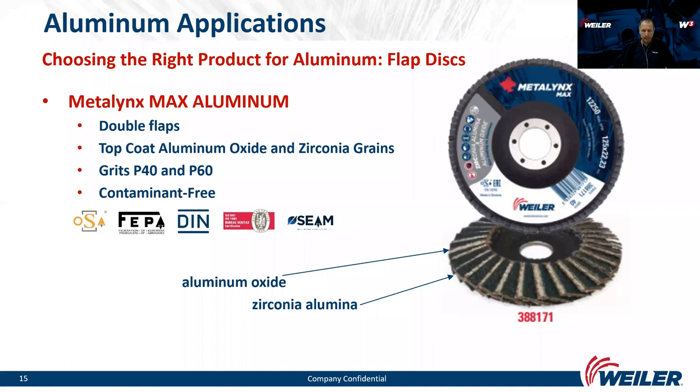Aluminum that is exposed to the atmosphere contains an oxide layer. To remove this layer and to clean the surface, we use a flap disc or stainless steel brush. Later on, I will provide you more information about brushes and non-woven material.